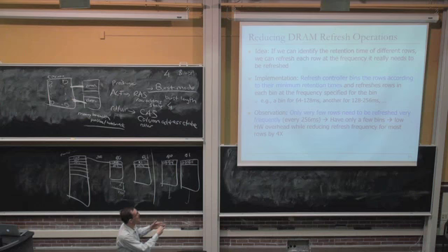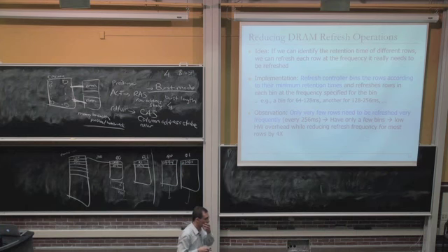Right? And then you can add another bin, if you will. That ensures that most of the rows are going to be refreshed at 1024 milliseconds, if you will. You have more hardware overhead, but now you cut down the refreshes by 1024 divided by 64. Is that 16? I guess it is 16, yes. 16x. Do you create these bins dynamically each time you run?